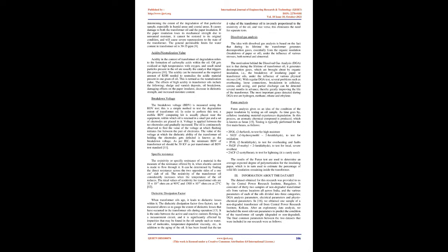The effects of high acidity in transformer oils include the following: sludge and varnish deposits, oil breakdown, damaging effects on the paper insulator, decrease in dielectric strength, and increased moisture content.